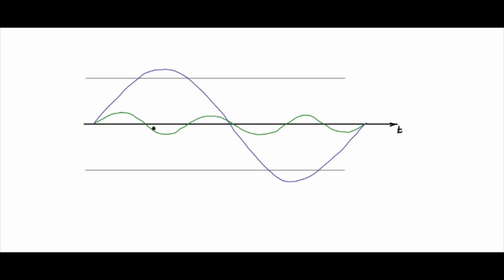So if a triplen is injected in a three-phase system, it is not going to affect because it is not providing a rotating phasor. And therefore, when I subtract it, you will see that the top portion gets subtracted because of this. So you will see that the wave shape takes a shape something like that. So you will see that this is just within the 100% modulation.